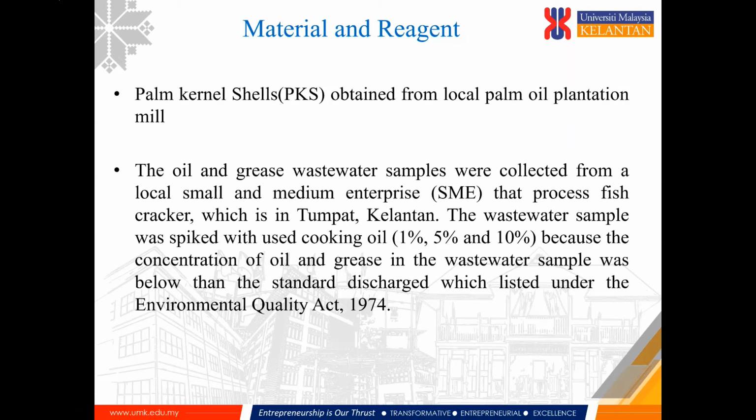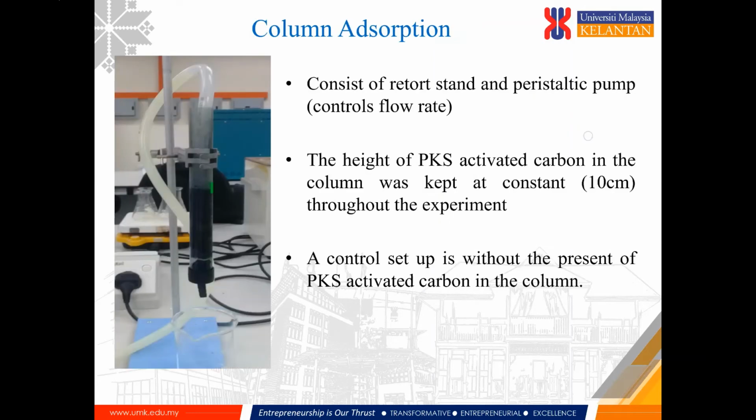Therefore, for this experiment, the wastewater sample was spiked using used cooking oil at 1%, 5%, and 10%. This is the figure for the column absorption setup, consisting of a retort stand and a peristaltic pump to control flow rate. The height of PKS activated carbon in the column was kept constant at 10 cm throughout the experiment, and a control setup is without PKS activated carbon in the column.